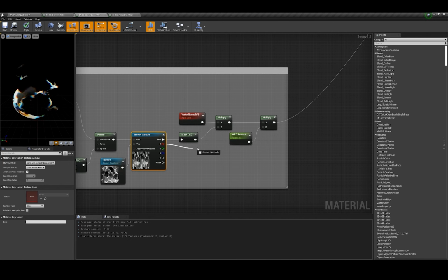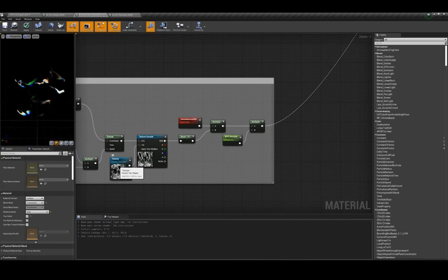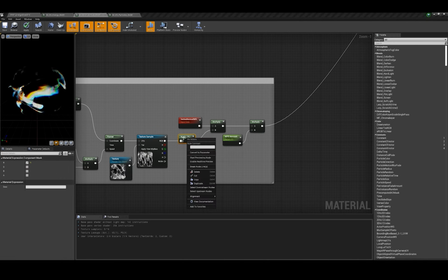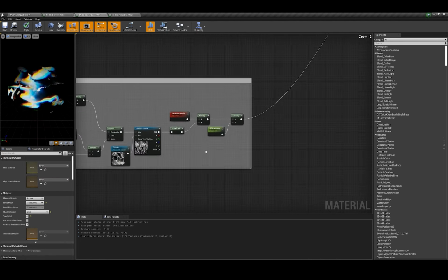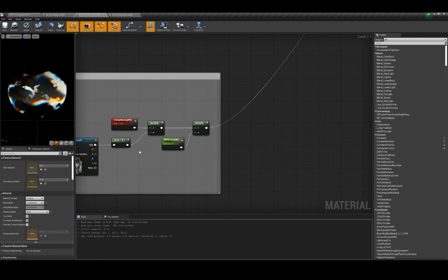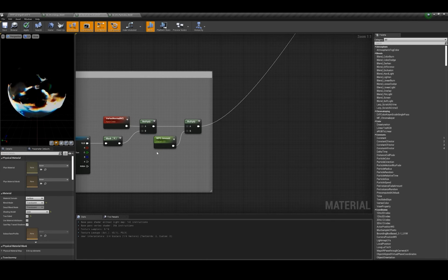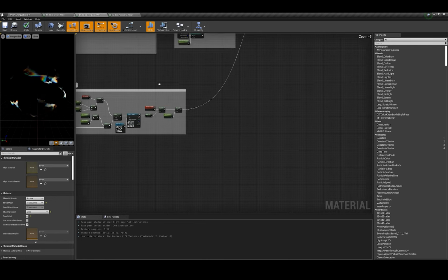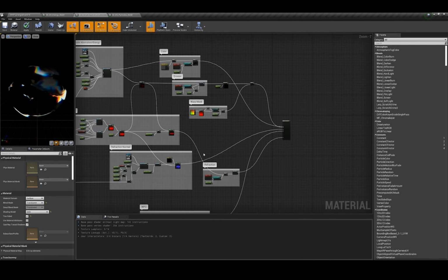And this is really not important. You could have just done the red value again. This is in case I change this to a texture that's packed. So if I wanted to do a packed texture, I could do this, and I could convert this to a parameter too, so you can choose your channels along the way. So some things are just a little arbitrary just because there's extra functionality needs that I may have in the future. And so I've just set them up that way. And then there's our world position offset amount, which I'm just defaulting to 0.